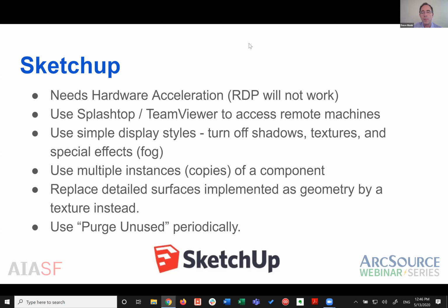Yeah. Rohit, there's a question about when sending links from BIM 360 to customers, do they need an Autodesk login to view? No, they don't. You can customize that link so that it doesn't require them to log in. You can send it to anybody who needs to take a look at the model. You can also make it private and constrain it to only the people who have an Autodesk login to be able to view that. So those are all customizable, but yes, it's not a prerequisite.